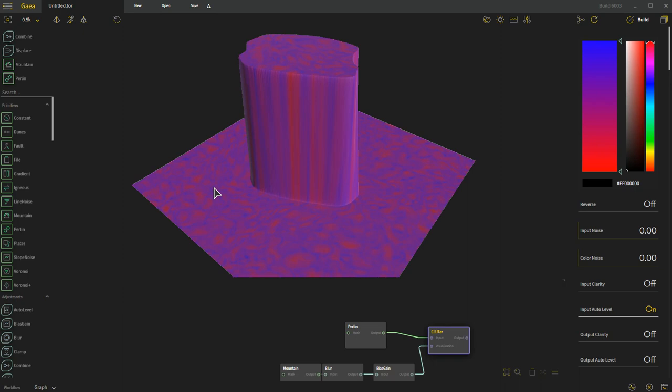And so you can transfer it from one version to the other via something called transfer maps, which is on the rendering lighting category. Transfer maps will allow you to send from a source object to a target object. So those are some ways in which you can deal with this situation.